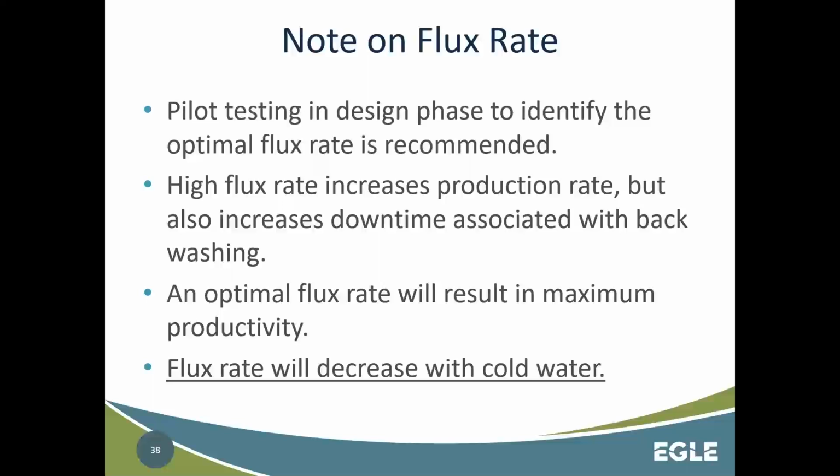So in terms of the filtration rate, theoretically, if you maintain your integrity, you can have an extremely high flux rate or an extremely low flux rate and still get the same turbidity removal performance, theoretically. However, pilot testing in the design phase is recommended to identify what your optimal flux rate would be.